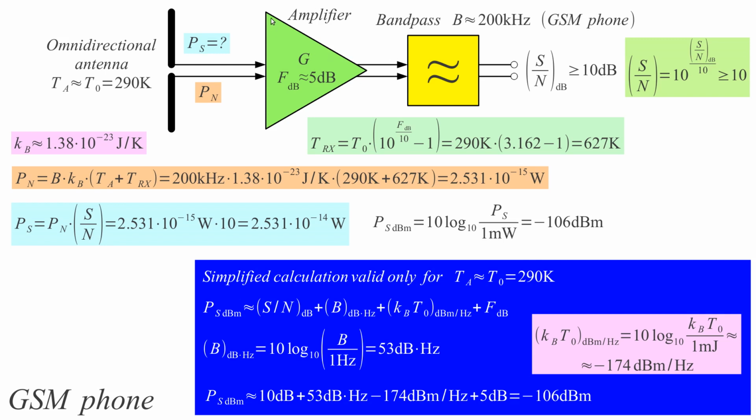And the noise figure of the amplifier is around 5 dB. Why is it not better? Because semiconductors can do it better, but we also have other components. We have an antenna switch between the receiver and transmitter, and an antenna filter. We also have requirements for the dynamic range and the distortion in this amplifier, so we cannot just optimize it for the noise figure. So 5 dB makes sense here.